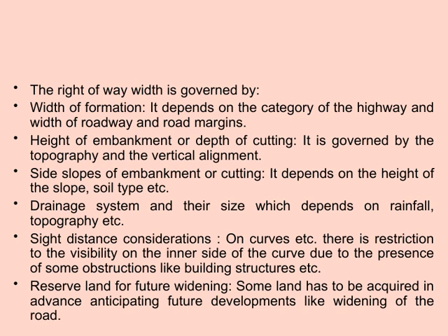Then, we consider the side slopes of embankments or cuttings. These slopes depend on factors such as the height of the slope itself and the soil type. For example, loose or sandy soils might require gentler slopes to ensure stability, which in turn affects the width of the right-of-way. Drainage systems are also crucial.